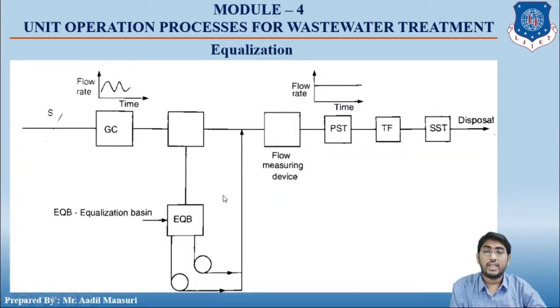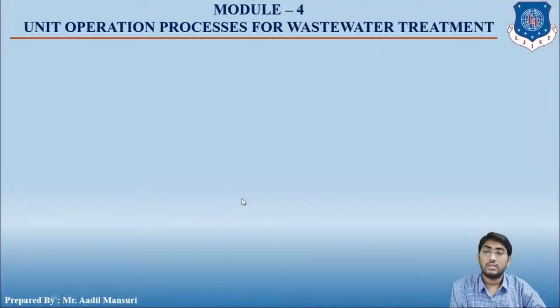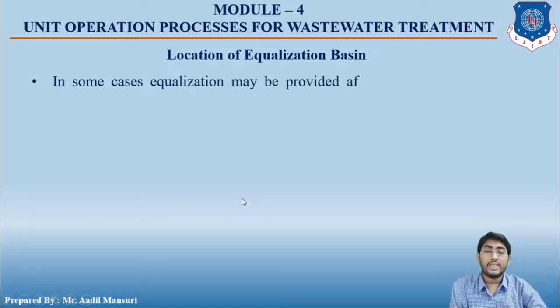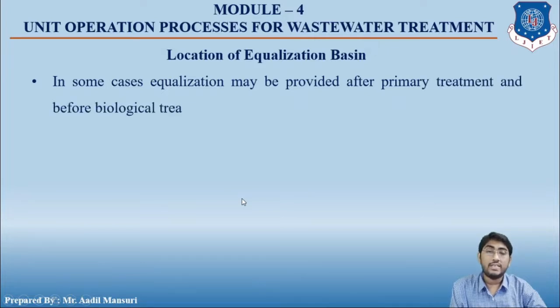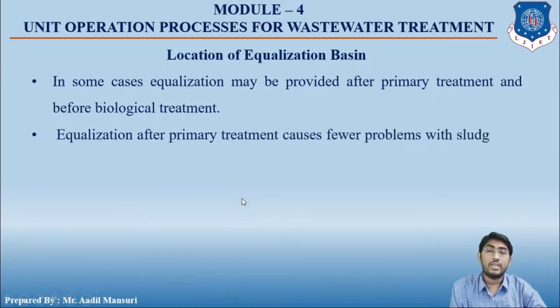So this is another type of equalization basin. Next is the location of the equalization basin. In some cases the equalization basin may be provided after preliminary treatment, that is primary treatment, and before the biological treatment.